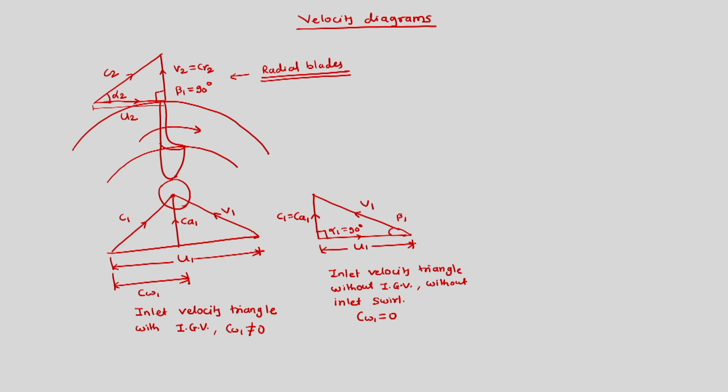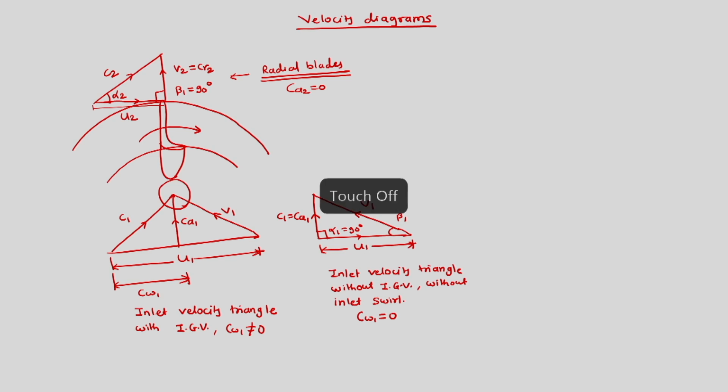Here we will have axial velocity completely converted into radial, and axial velocity is 0 at the outlet. Having said this, we will move ahead and decompose the same situation, where we are supposed to feel that we are at the impeller I, and at this inducer of the impeller we will try to plot. This is the inducer of the impeller and this is the complete impeller. We will see how the situation is different with IGV and without IGV.